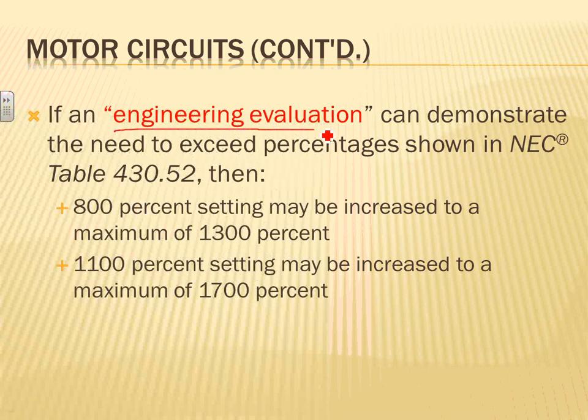Engineering supervision. This is where you guys exercise your judgment, because you're willing to go to court for it. Sometimes you can exceed all these values. You can see how much you can exceed it. You can demonstrate the need to exceed, but you have to have a need to exceed it. I've been on a project, guys, where after you size based on the code, the circuit breaker trips because of inrush. As an engineer, you can exceed it. Here's a couple of values that you can use to exceed what the code is asking for.